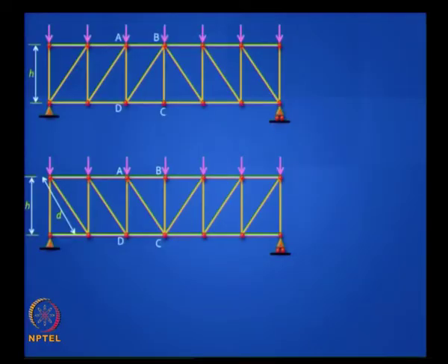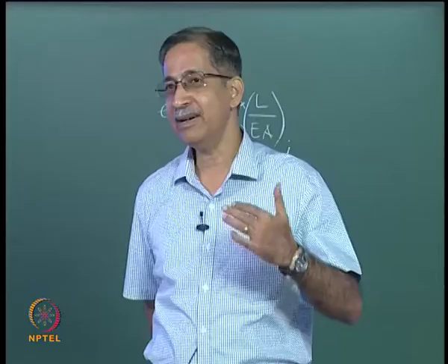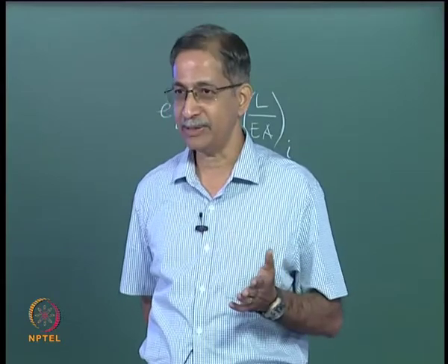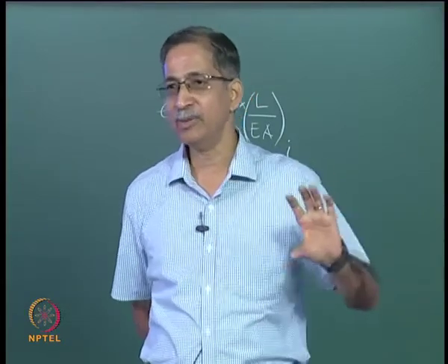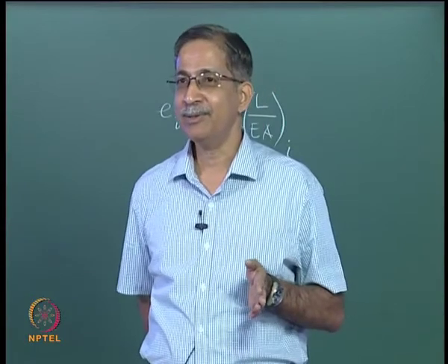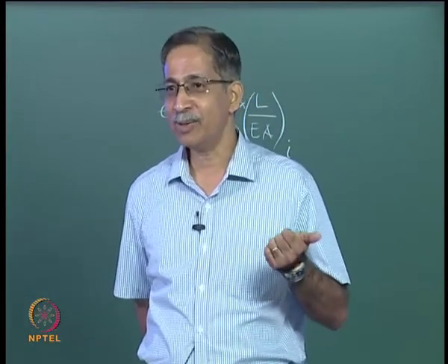When you cut the beam at any place, the reaction at the left side support is upward, so the shear acting where you cut will be downward. So the member there, as it is aligned downward, will be having a tension. So in the second truss, the diagonal members will be in tension, and in the first truss, the diagonal members will be in compression. That you get from the equivalence with the beam when you do method of sections. So we should prefer the bars going into tension.